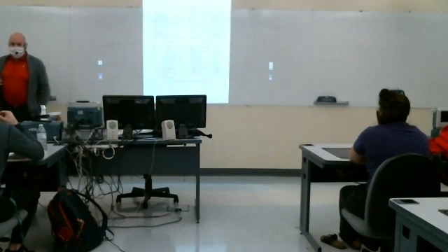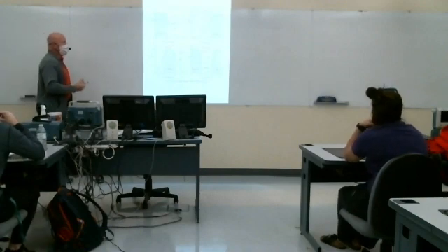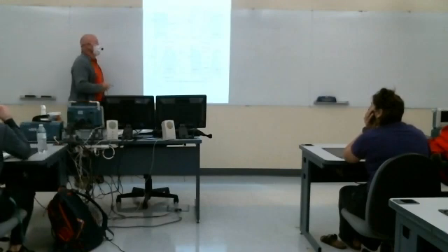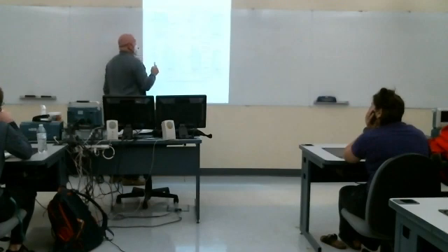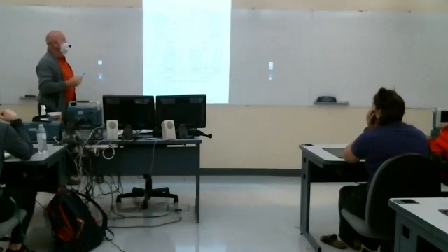Of course, higher order filters require more capacitors, more inductors, more resistors, and are consequently more expensive. The more components you use, that's a consideration if you're going to mass produce some sort of object. So this is what's called a low pass filter. It has a maximum value here. This is actually the magnitude response of our frequency response. It's what we're plotting here. We classify filters based on their magnitude response, kind of ignoring the phase response.